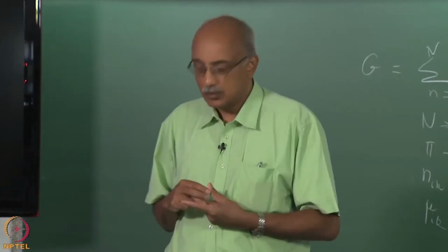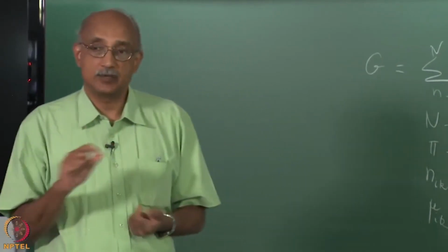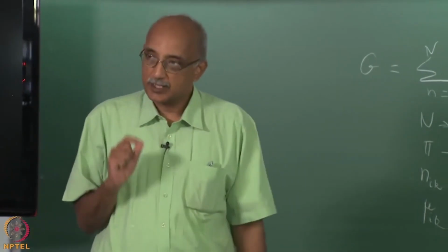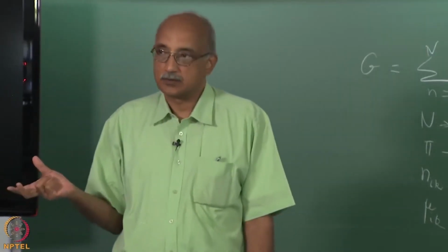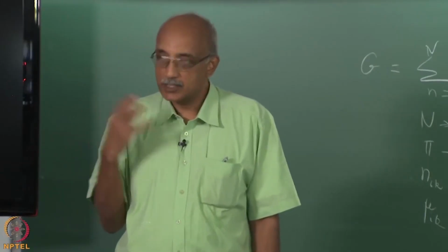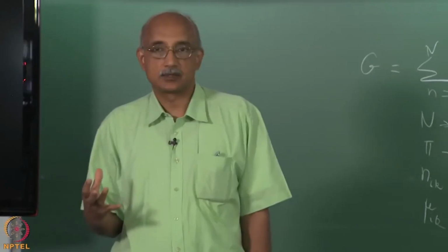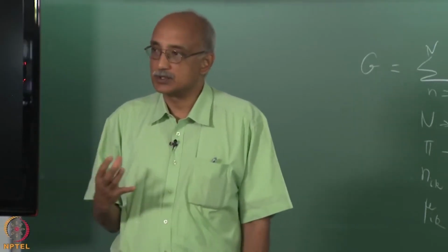So, when you talk about mass conservation, here is where the differentiation between PVD and CVD becomes very evident. In physical vapor deposition, there is no transformation of one species into another, right? If you put in SiH4 in a physical vapor deposition reactor, it will stay as SiH4. There will be no conversion to various other compounds in the system.